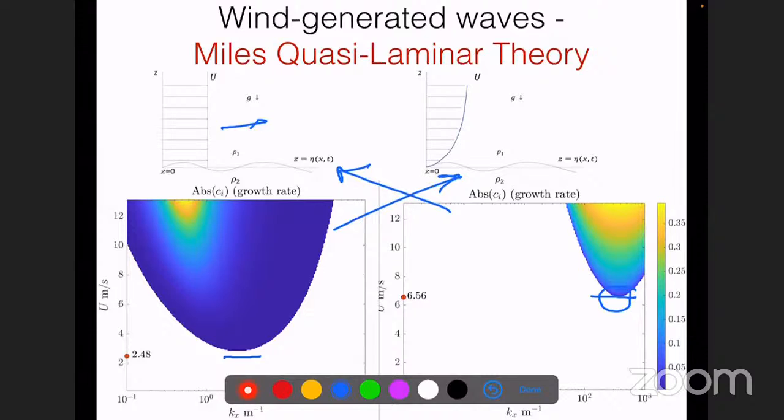Unless you make an argument like the boundary layer, where the flow is varying much more slowly in the x direction, or for unsteady problems, if the flow is like a diffusing problem. If you have a vortex which is diffusing significantly slowly, and you are trying to probe the instability, you can either assume the flow to remain frozen, a perfect steady problem, or you can be a little better and say that the flow is evolving, but the evolution of the base state is happening on a time scale much larger than the instability time scale.